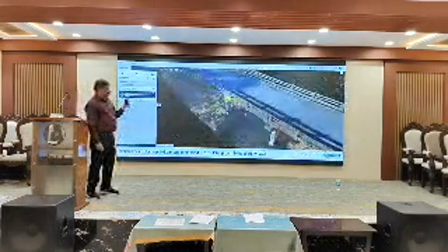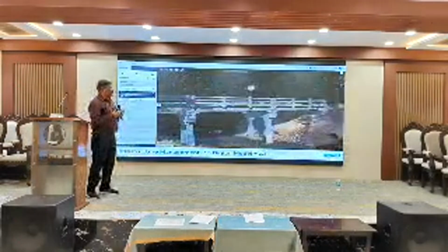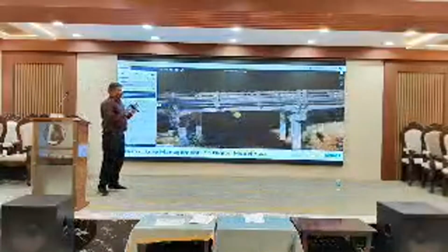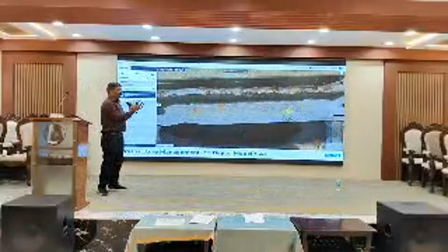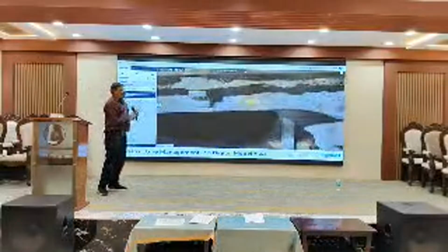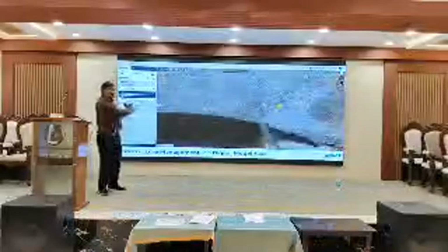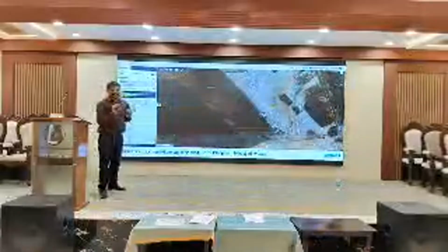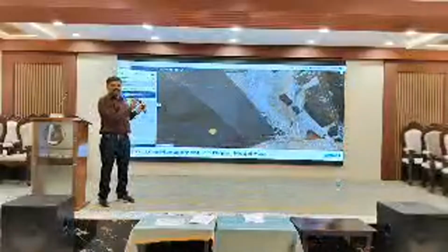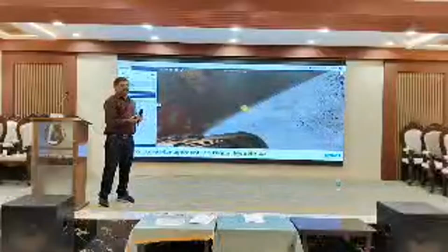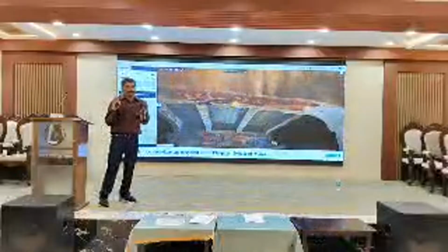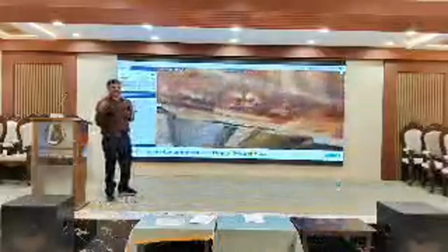So what we are finally looking at is like a grid structure. We have gone to the grid structure. We have taken different directions of photos, geotagged RGB images, and then reconstructed the entire structure. It's not just a video. It's actually only taken from the images. This 3D model of the structure has been constructed using the principle called photogrammetry. There are open source tools as well, like Pix4D, and Bentley's ContextCapture.